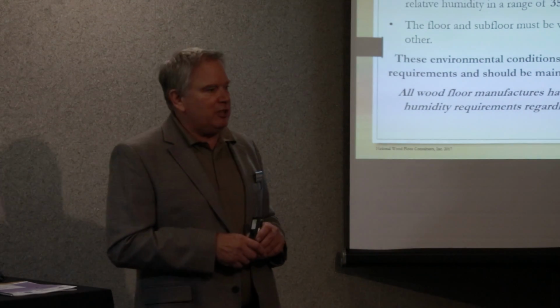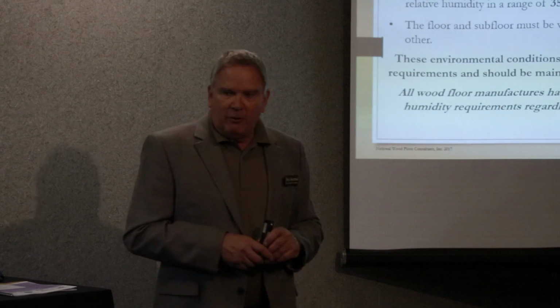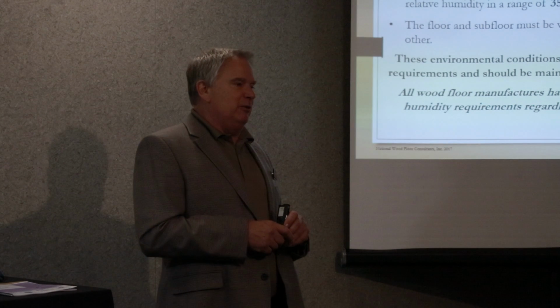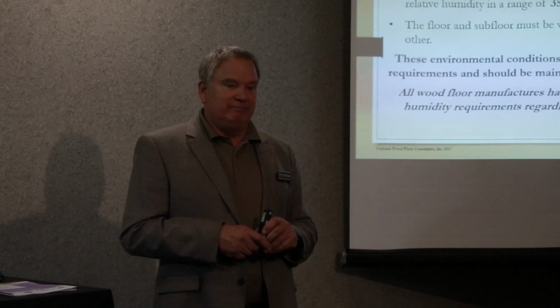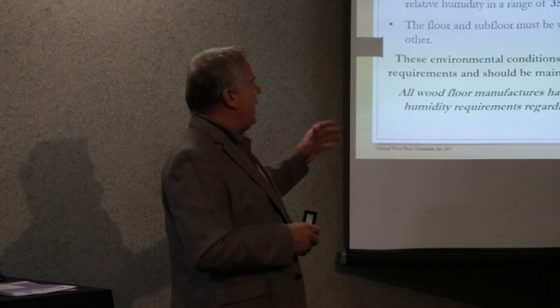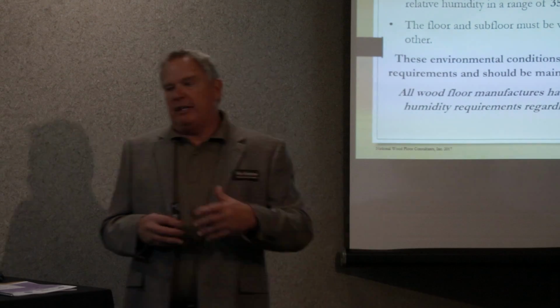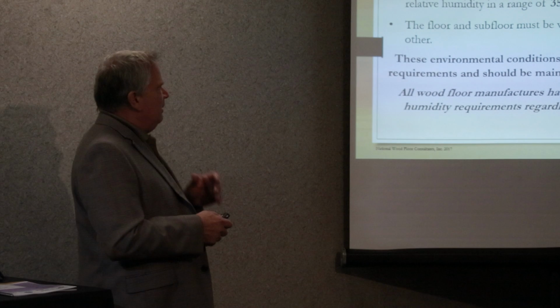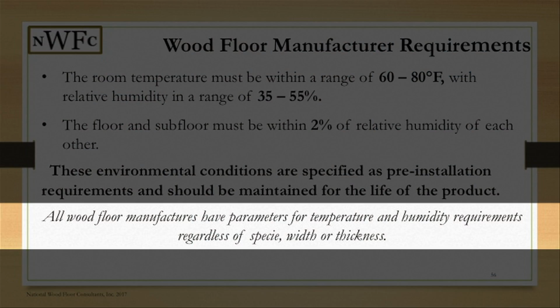Can you imagine what the construction site was like for those 6 weeks while a tile setter and everybody else were still in there doing taping? And so therefore, when we're putting floors in, the environmental site must be a controlled environment for humidity. Regardless of species or thickness, the parameters must be followed for temperature and relative humidity.